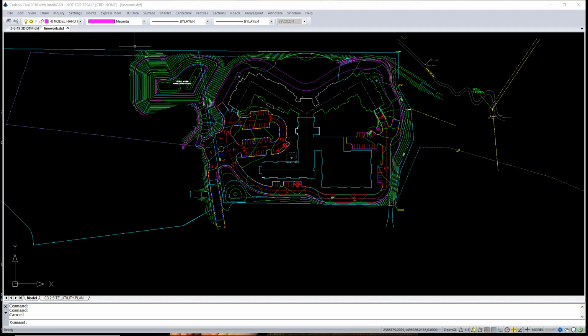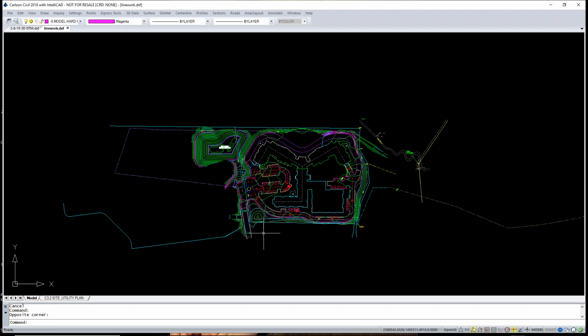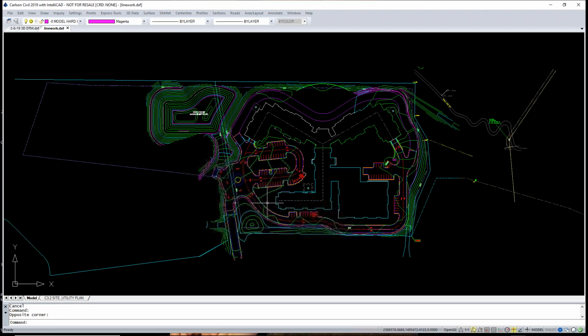I use Carlson, so I know you can have the Surface attached to XML and Trimble Business Center, but I'm not familiar with Trimble Business Center. Just played with it a little bit. So I don't know if you attach a TTM, their actual Surface file. I know if you just attach the DXF line work for the 3D faces, it doesn't come in on the XML as a Surface on the machine control that way. So it's probably a TIN or a TTM or DTM file.